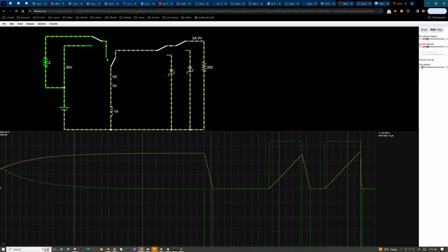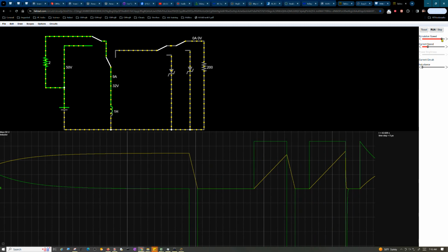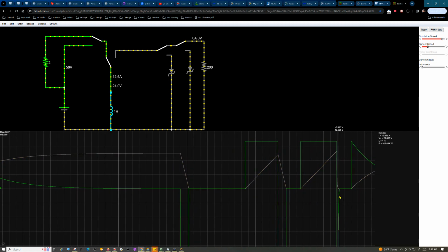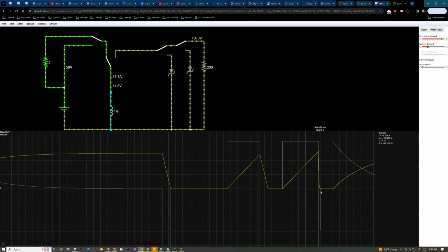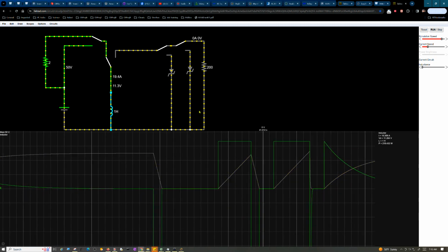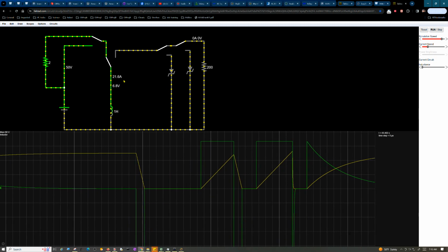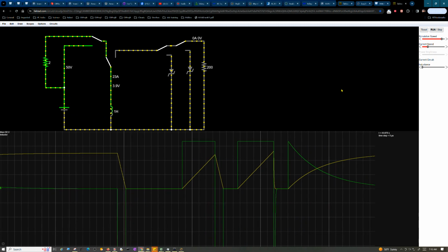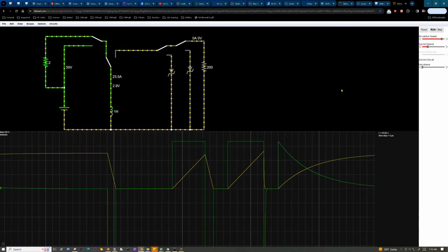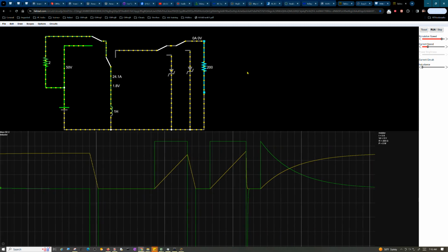Now let me go ahead and switch it back over to resistor and get it charging. I want to discuss this. But you can see that it generated a 5 kilovolt pulse, but it discharged really quickly. Again, its current never exceeded the original 26 amps or whatever we had it at, but the voltage made it discharge really fast and non-linearly, because this is a non-linear discharge.